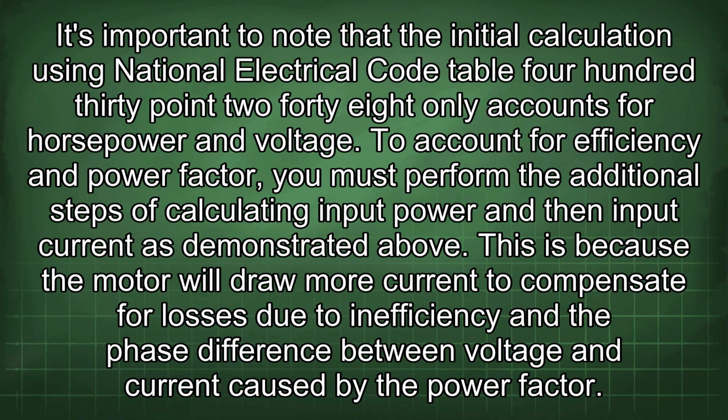To account for efficiency and power factor, you must perform the additional steps of calculating input power and then input current as demonstrated above. This is because the motor will draw more current to compensate for losses due to inefficiency and the phase difference between voltage and current caused by the power factor.